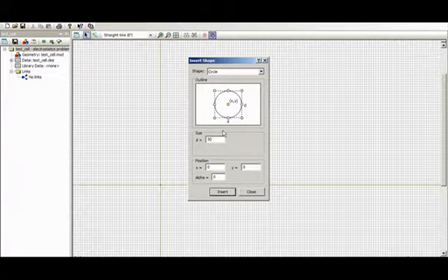Now I'm going to create a second circle, which is going to define the outer boundary of the cell, and we need a separation of 7 nanometers between the middle circle and the outer circle. So if I type 50.007 microns, that'll give me a membrane thickness of 7 nanometers. So I'm going to insert this. Okay. And let's close this.